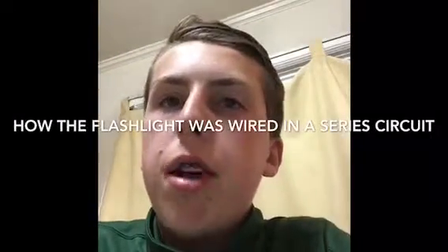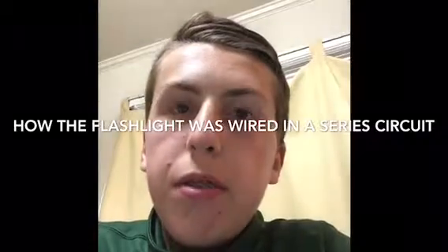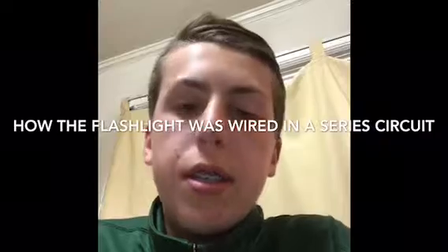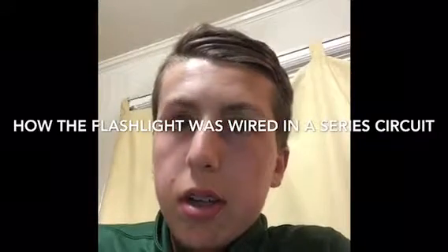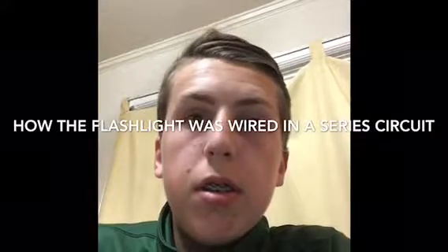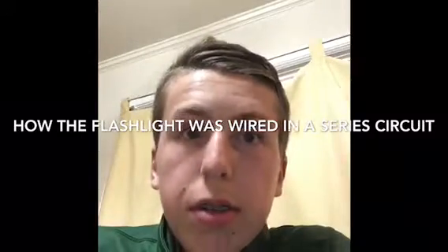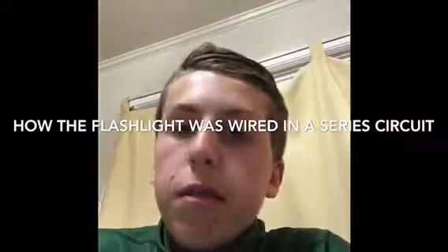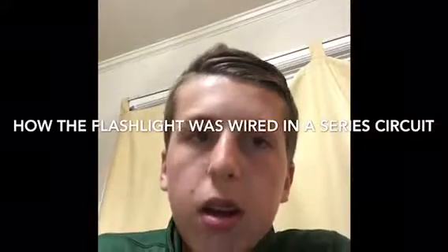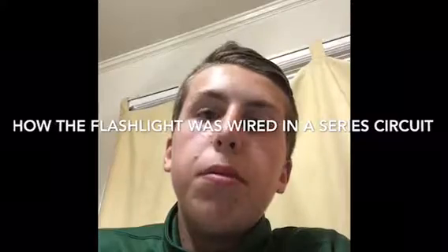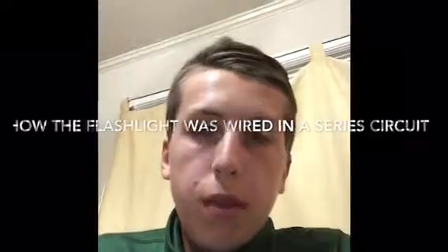In a series circuit, there's only one path for the voltage to travel. The two light bulbs have to share the wire. The voltage and current is less in a series circuit than a parallel circuit, but there's more resistance. This is due to the fact that resistance is increasing, so the voltage and current would decrease because of their inverse relationship. The current in the series circuit was 0.07 amps for both of the bulbs. The voltage was 1.57 volts for both of the bulbs.